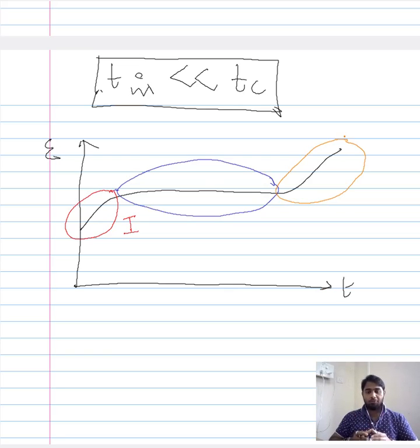Supposing the plot before you includes the instantaneous creep section, then your stage 1 should comprise of instantaneous creep and the transient creep. If the plot before you begins with the transient creep alone, then your stage 1 should exclusively be defined by the transient creep. This is because it all depends on the time taken by the material to complete the instantaneous creep. If you have a crystalline material that takes a definite period of time that is relatable to the overall creep testing, then stage 1 of that material would include both instantaneous creep and the transient creep.